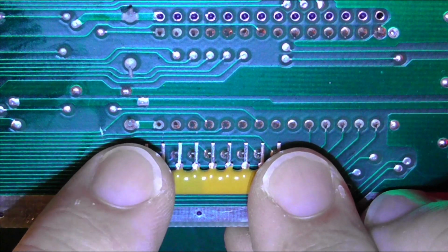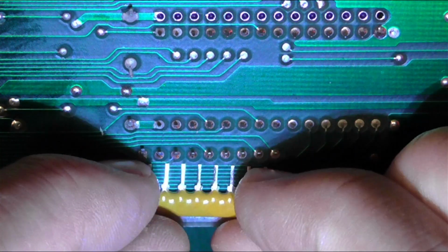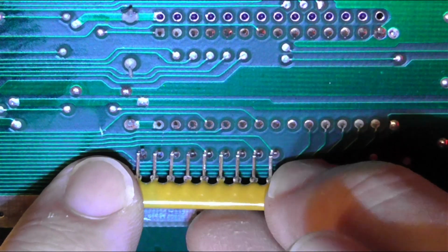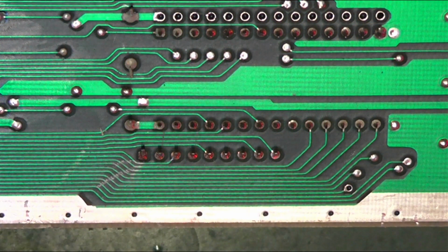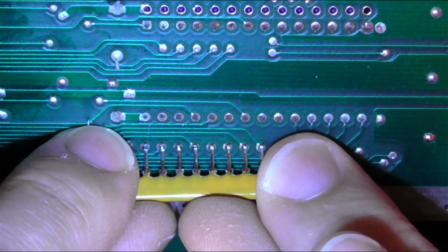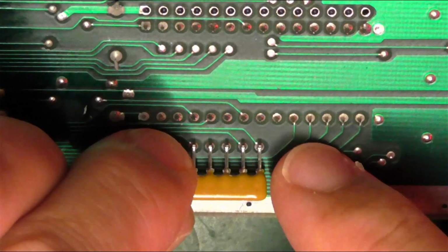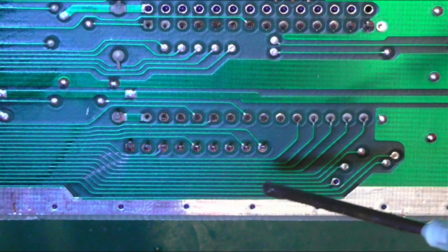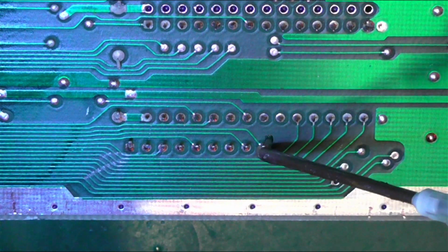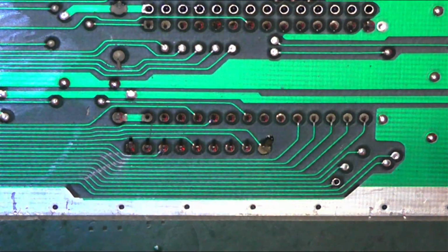So we'll try and get this in here. Should I go something like that? Maybe that might make it more flush, but I kind of want them to touch the base where the actual solder is going to be, where the pad is. I think I might have to get in and anchor one end like that, and then come at it. So let's get some flux on that end there. Introduce some new solder.